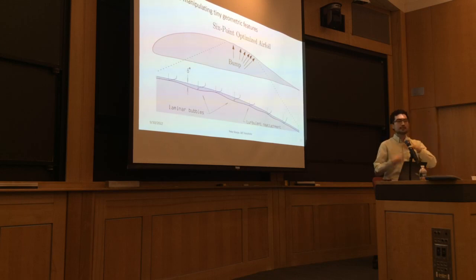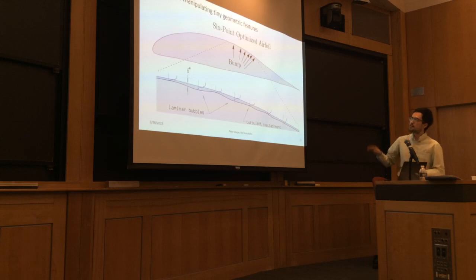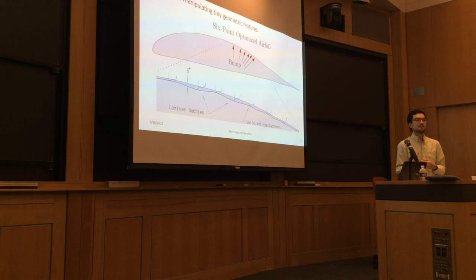Yeah, that's a great question. So as you said, as you get to higher Reynolds numbers, that laminar separation bubble becomes smaller. You could trip the flow at the beginning. This is an illustrative example. There's another example in the paper about a high-speed flow, which is a transonic airfoil design. And one of the things that you'll see is, so transonic airfoil design is dominated by the shock formation. You really want to minimize that or at least delay that.